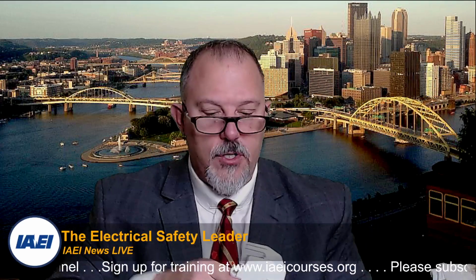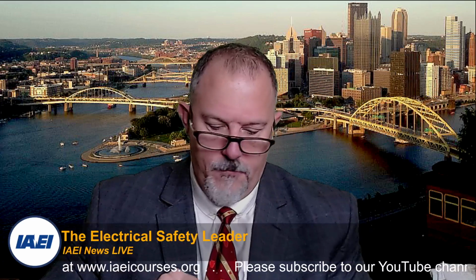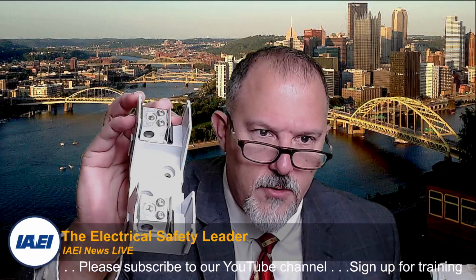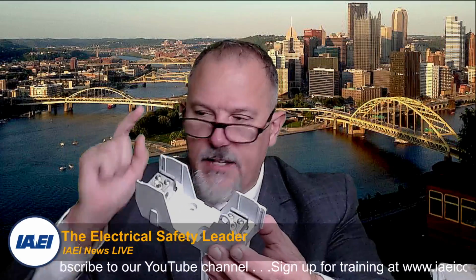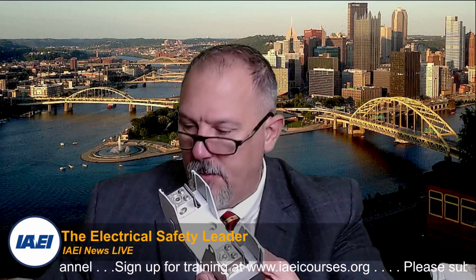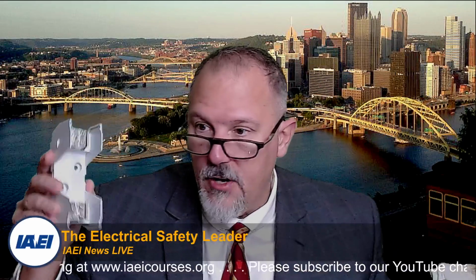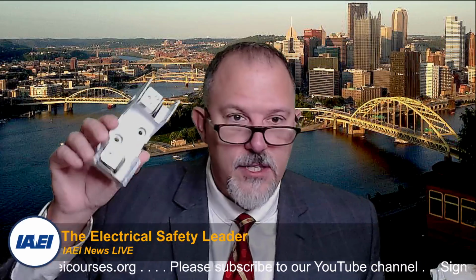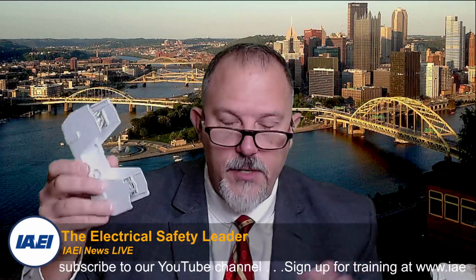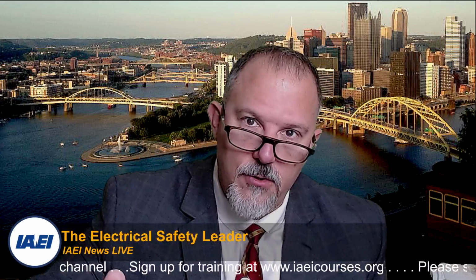This is a fuse holder. I'm going to pull this fuse out. So this is a fuse block. And you'll see there's a terminal in here. This is what you need. This is what this informational note is talking about. It says a fuse comprises the parts that form a unit capable of performing the prescribed functions, which is opening. That's not what this does. It says it may or may not be the complete device necessary to connect it into the circuit. So most fuses require a device like this, which we call fuse blocks or fuse holders, that enable you to insert this into the circuit.